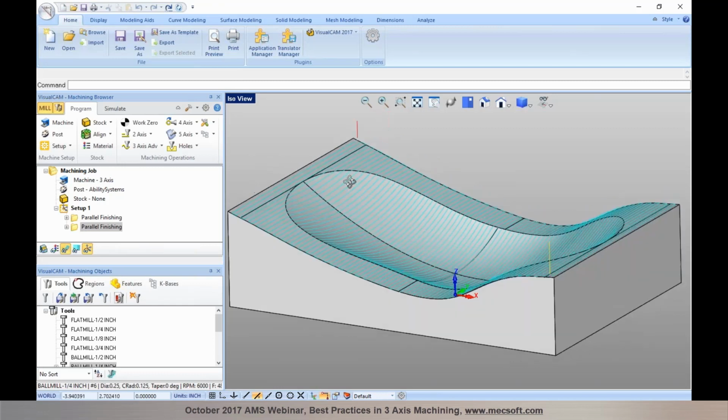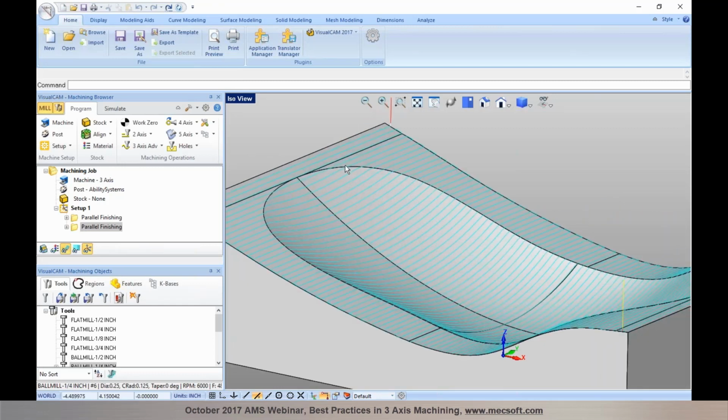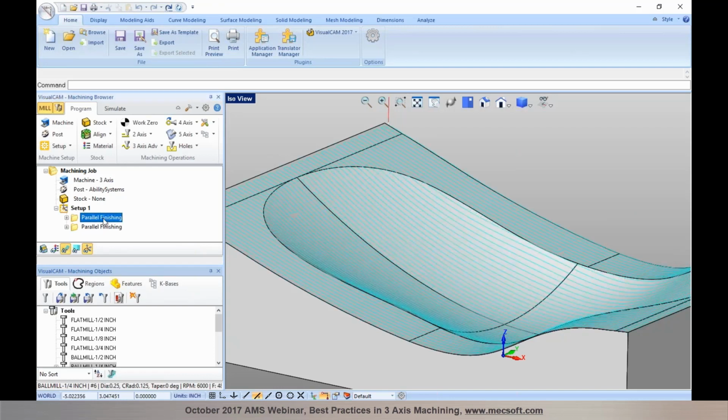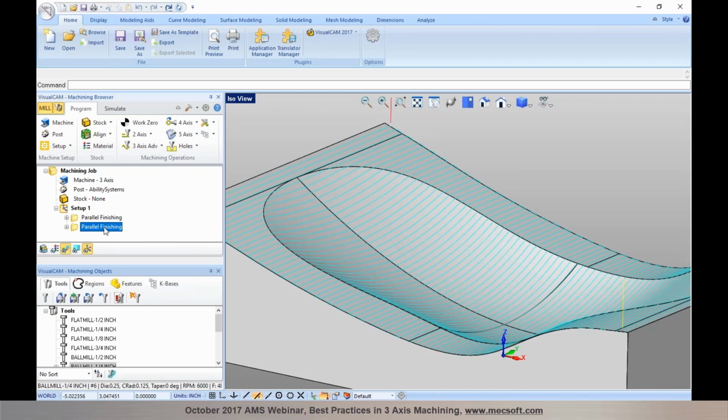Just to give you a quick overview of how to control the surface finish, you could be changing the direction of cut, the angle of cut, to eliminate some of the scalloping and to improve the surface finish based on the geometry and the toolpath operation and strategies that you're going to be using. You can also refer to the webinar that we had on feeds and speeds, to see how to improve the finish based on the material types and what feeds and speeds you can set to get an optimal surface finish for the material.